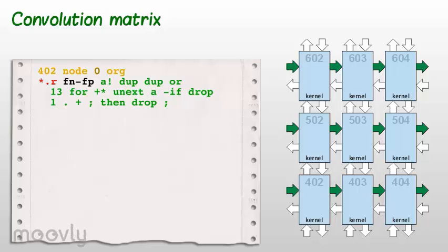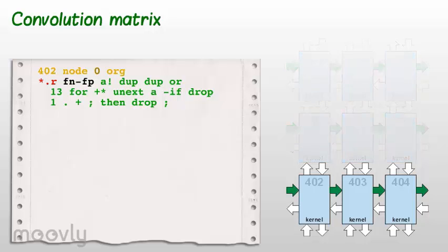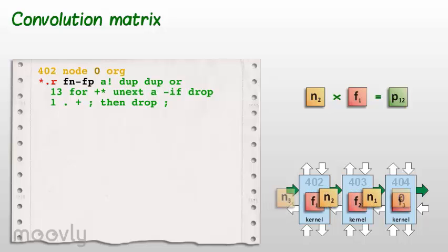Data flow rate is a critical parameter for the convolution module. Since all 3 lines of the matrix execute the same code, I will demonstrate the approach used on the bottom line of the matrix. As explained earlier, pixel values to be convoluted are shifted into the matrix eastward, and in each step a multiplication of the pixel value and the corresponding convolution factor is carried out. Thus, we have 2 streams of data. The first one moves pixel values into the matrix. The second stream moves partial products out of the matrix.